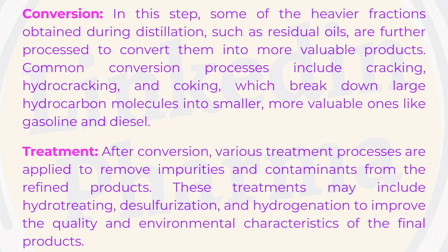Conversion. In this step, some of the heavier fractions obtained during distillation, such as residual oils, are further processed to convert them into more valuable products. Common conversion processes include cracking, hydrocracking, and coking, which break down large hydrocarbon molecules into smaller, more valuable ones like gasoline and diesel.